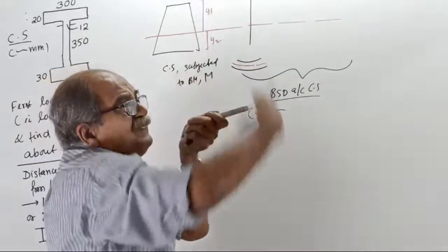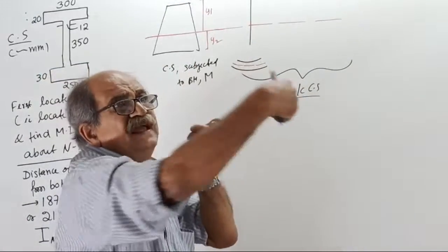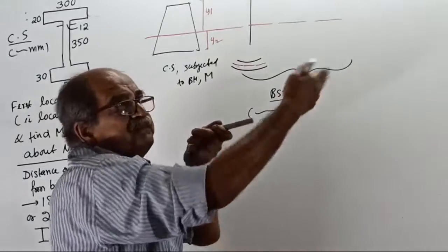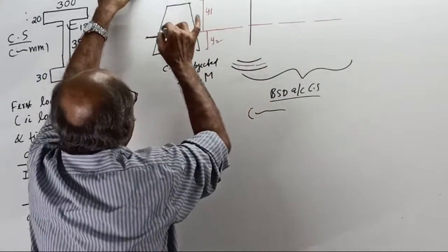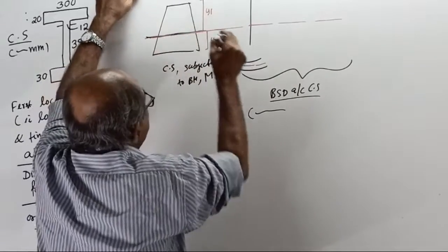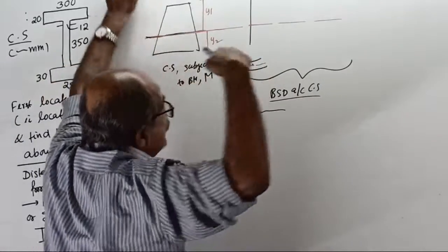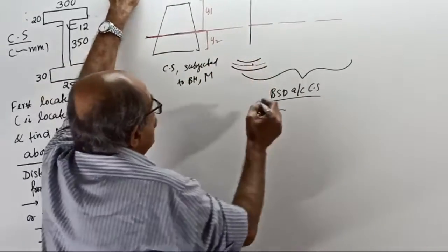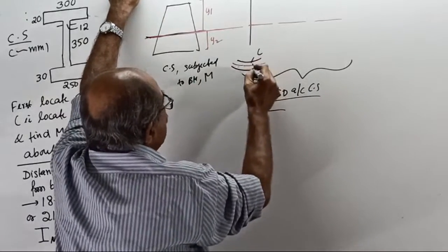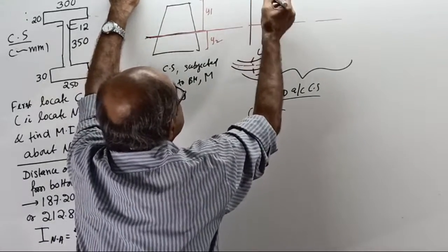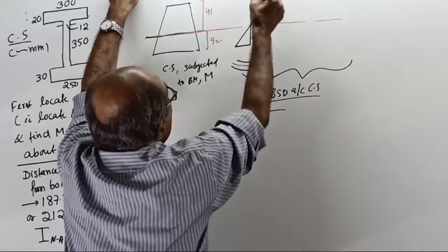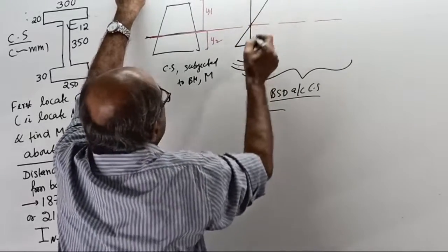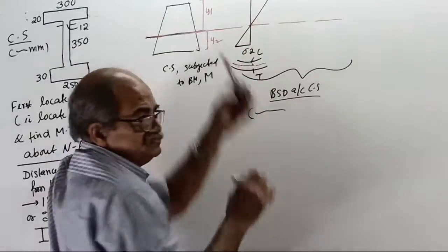And when you take the cross-section, you can see the corresponding intersection line here. That plane with the cross-section is the neutral axis. Then the top will be compression, the bottom tension, and the stress diagram will come this way. Whatever is there, I call sigma 1, I call sigma 2.